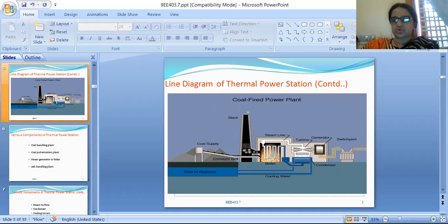If you want artificial cooling, or artificial condensation, the water which we pass through the condenser, with its increased temperature, will be passed to the cooling towers, by forced fans or by natural air, by natural method or by forced flow of air.